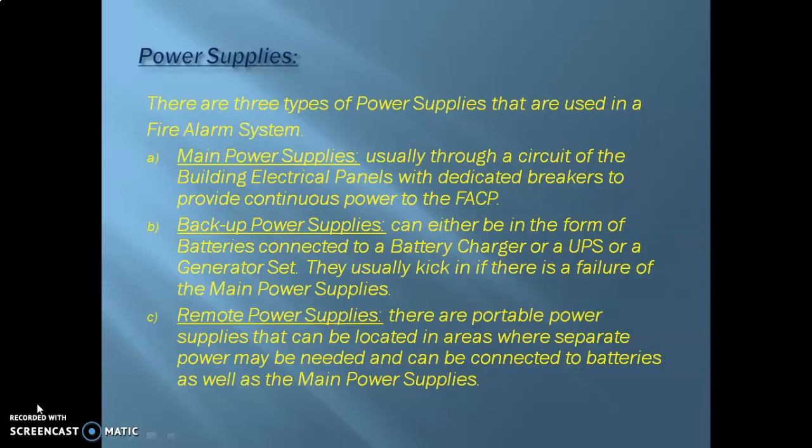So in that case, you can use these remote power supplies and connect the devices to them. Of course, in some of these there are options of connecting backup power supplies even to these remote power supplies. You can provide batteries for them, or you can connect them directly to the main building power supply as well. So you have all of these options available as per the manufacturers. With that, that covers the power supplies components for the fire alarm system.